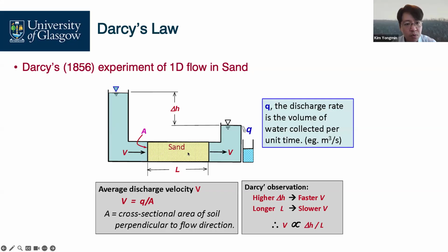Because we can consider these 2 points, we set up our datum here, right? The datum is the same for point A and point B, but your water standpipe height differs. At point A, your standpipe is here, because this point is connected to this water height and exposed to atmospheric pressure. Can you remember? Pore water pressure is measured relative to atmospheric pressure.